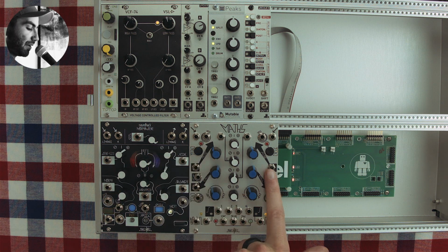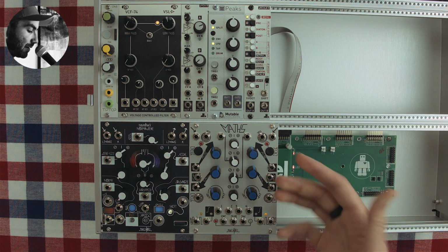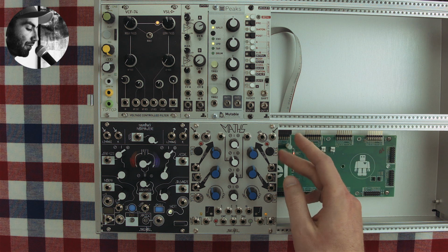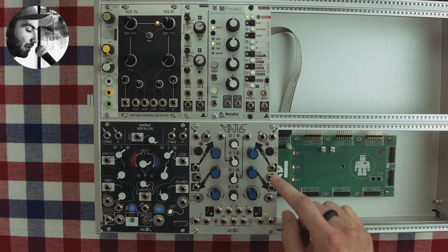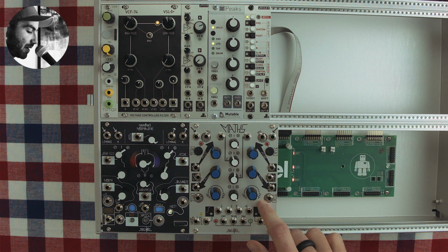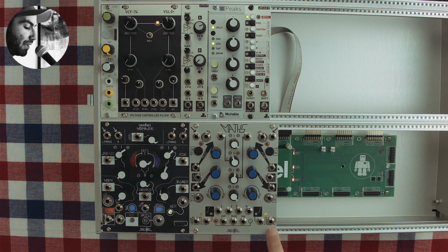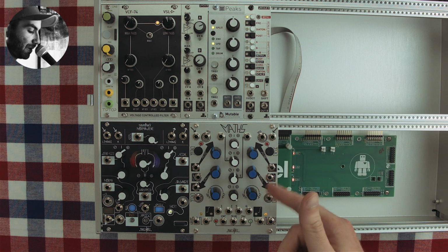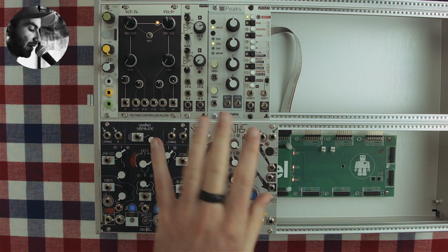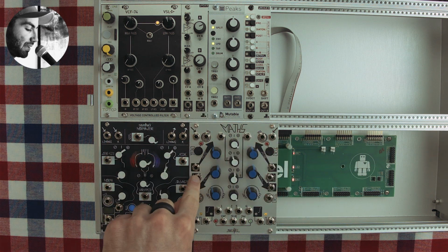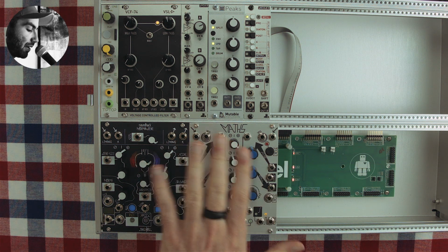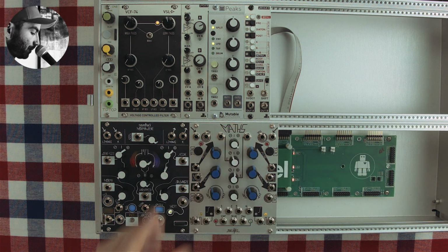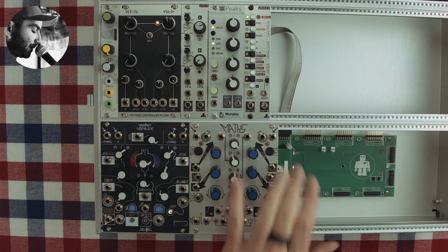And then if we jump over to the other side, we have channel 4. And I don't have to go through this. You have exactly a mirror image here. So same signal input, trigger input, the rise, fall, exponential, logarithmic, cycle, switch. The only difference is here, instead of an end of rise, we have an end of cycle. So this gate will fire when it completes the whole cycle. So effectively when the fall phase is completed. And we'll go over what these things sound like and what the purpose of all of these things are later when we go over the demo. For now, just want to get over the basics of the front panel. All right, so that covers channel 1 and 4 here.